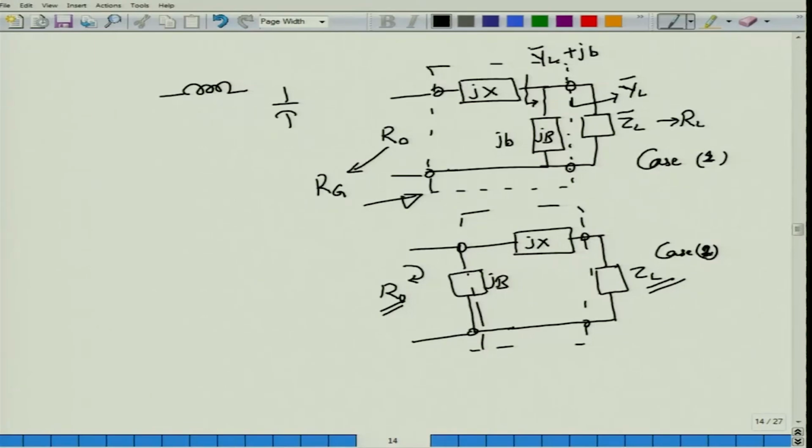So if I look at the corresponding impedance now, not the admittance, this is the admittance that I have. If I transform this, I should have a transformed impedance, let us call this ZL prime, of the form 1 plus jx, where x is the normalized reactance. Now when I add minus jx, again small x denoting the normalization, the impedance seen looking here will be 1 plus j0, which is the normalized impedance, and therefore we have achieved a match.